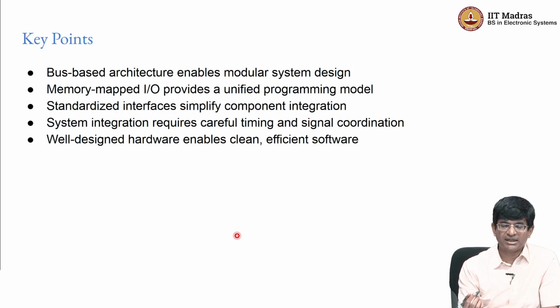Nowadays, as I said, AMBA and the AXI bus protocols are probably the most common standardized ones that exist. They happen to be open protocols, which is also good, which means that anybody can read up the documentation and implement peripherals that are compatible with those protocols. The actual integration into a large system requires careful coordination of the various kinds of signals used as well as the timing between the signals. And if we design the hardware keeping all of these things in mind, it enables us to write clean and efficient software as well.